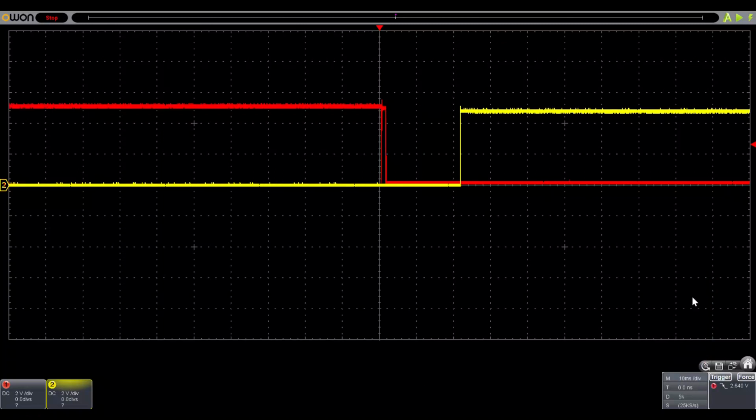To make the noise more evident, I have decreased the time per division, thus zooming in. You can plainly see that this single button push resulted in multiple spikes in the first 2 milliseconds after trigger. If the physical contact noise of the button press had not been ignored, this would have resulted in multiple triggering of the counter.